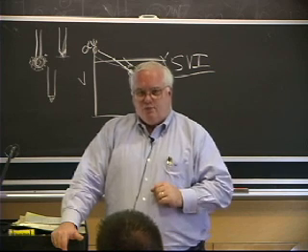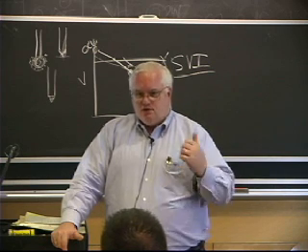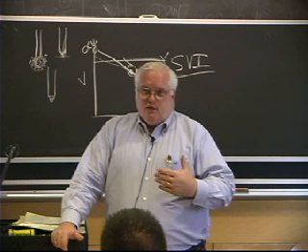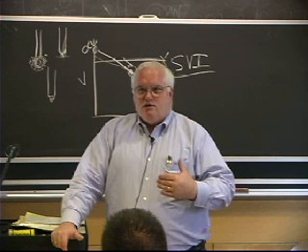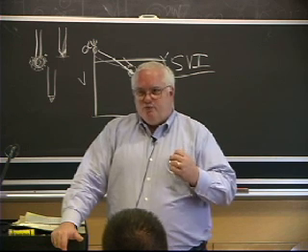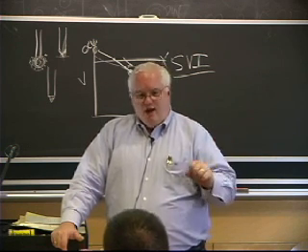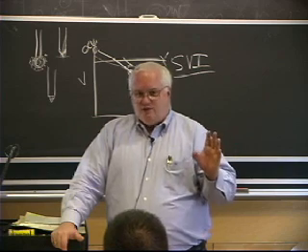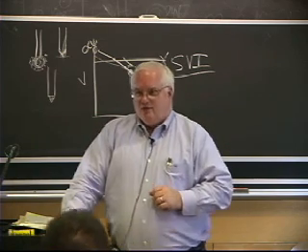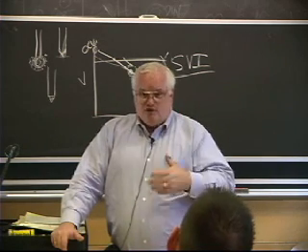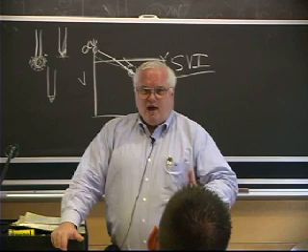You wouldn't want to do something like that with a welding power supply because the problem with welding power supplies is, I always tell students, they don't trip fuses. Okay, you've got them fused with enough power behind them that you can get 1,000 or 2,000 amps out of them if you go to a dead short. And so they don't trip fuses, and you can start fires with them and things like that.